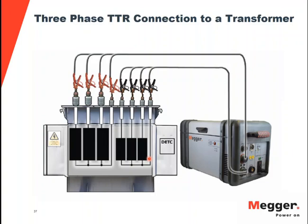Yeah, so on this, TTR you can do on all of them, and I would say winding resistance as well. Just always remember to be within the proper 1 to 15% of the rated current when performing the test with the winding resistance. So as long as you follow those principles, you can apply both TTR and winding resistance to transformers of all sizes.